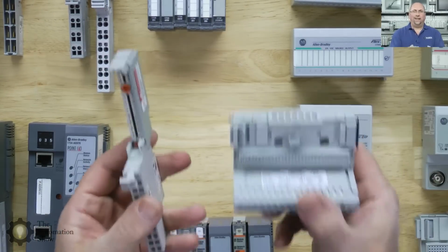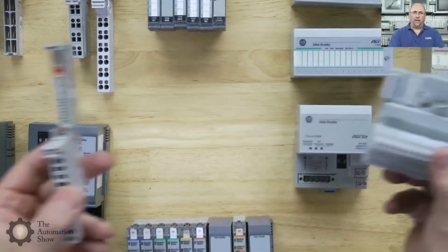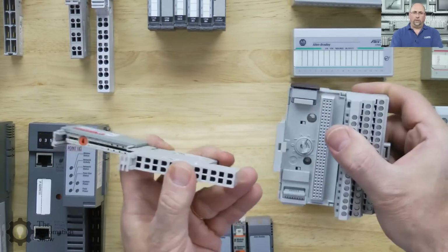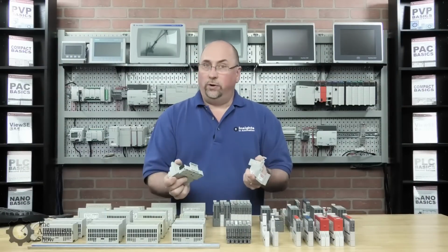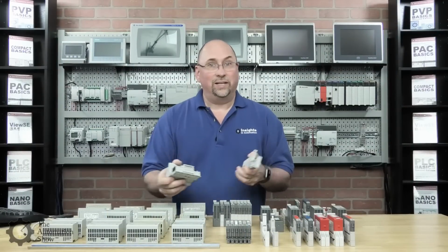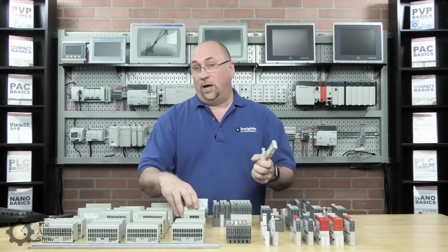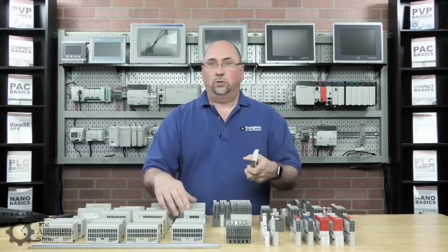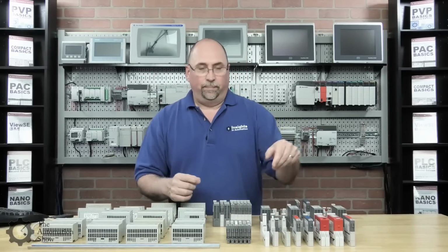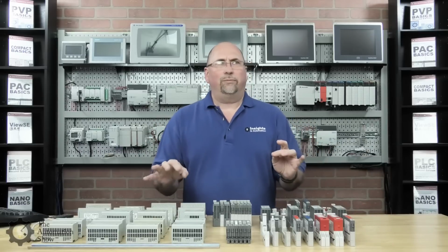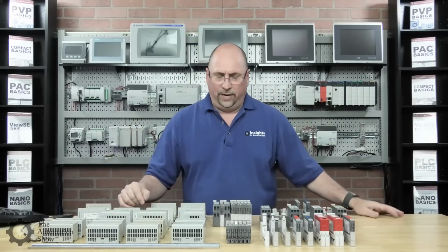And both these lines can be mounted either horizontally or vertically, okay? And that's important because a lot of times you'll want to mount it vertically if you're doing a retrofit and there's not a lot of space, right? So I know a lot of people have mounted FlexIO to actual supports or poles in their plants, which is really cool. So they both support that. Now, I think the only other line from Rockwell that supports that is the Flex 5000. Everything else has to be horizontal for the convection cooling. So keep that in mind.